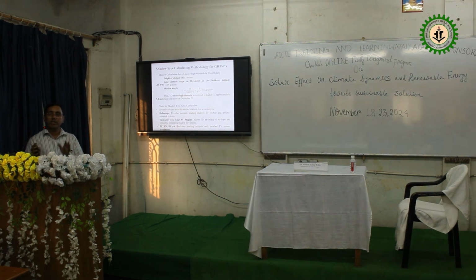According to that, what will happen? Shadow will come, then solar output will be less. So that calculation is also done in actual installations. For the shadow free calculation, the tools we have to use, we have already tried PVsyst and PV Sol, as well as the best tool, which is Helioscope. You can install it for your home also. Every setting will be there. This is sometimes also available free for 1 month.